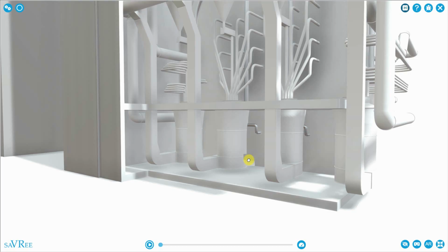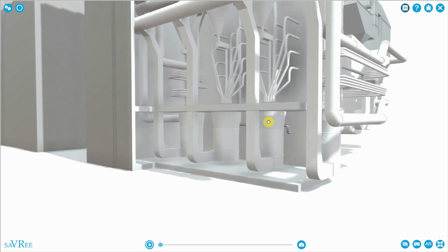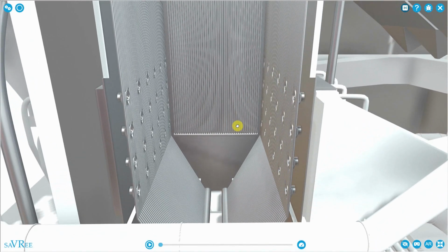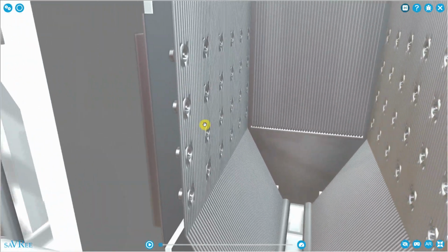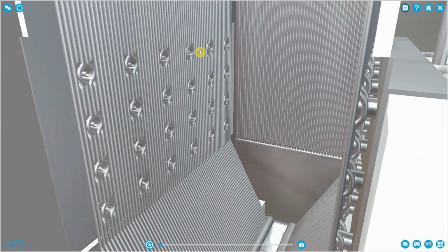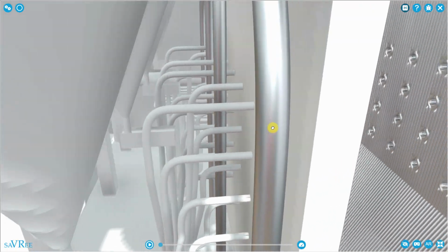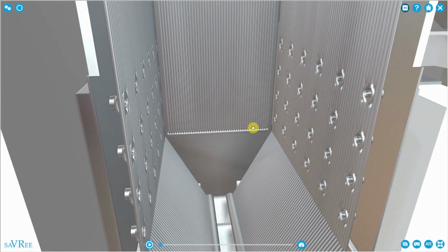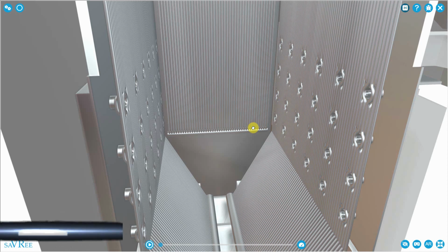We pulverize the coal and then feed it pneumatically into the boiler. The coal will actually come out through these holes that you can see in the side of the boiler, and they're on both sides of the boiler. The 2 main types of fuel feed system that you're likely to see are the pulverized type, which is the one we're looking at now, or the stoker type, which uses a moving grate in order to feed coal into the boiler.